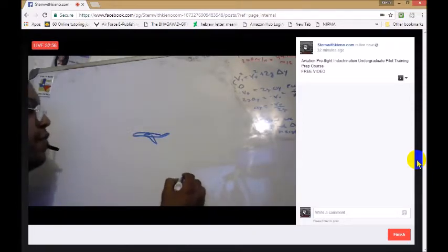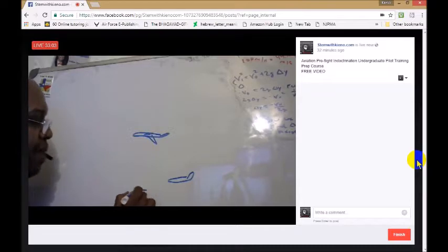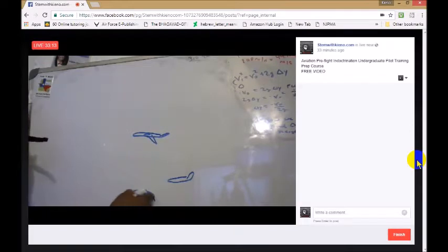In a dirty configuration, if you've ever been flying and looked out the window, you could see flaps extended, or even leading edge flaps, where we have extensions coming off the wing on the leading edge and the trailing edge. Basically what we're doing is increasing camber. Camber is just a fancy word for curve. The more curve that we have, the greater lift we can produce at a slower airspeed.